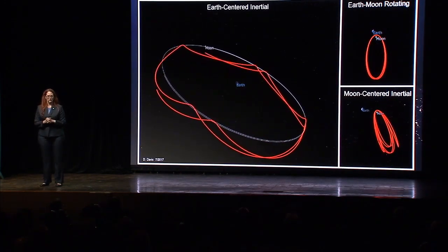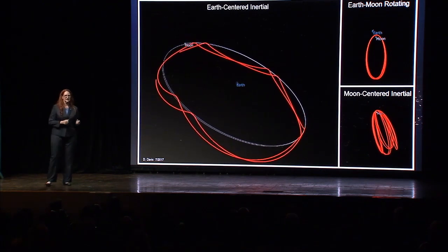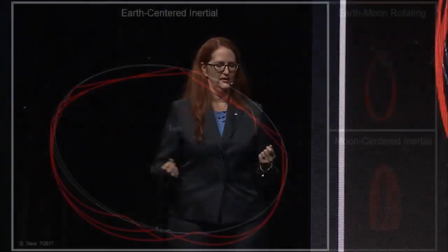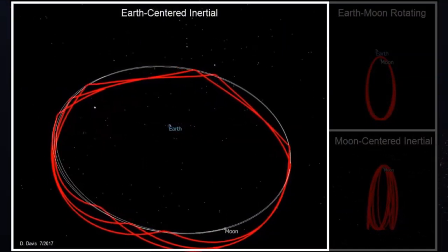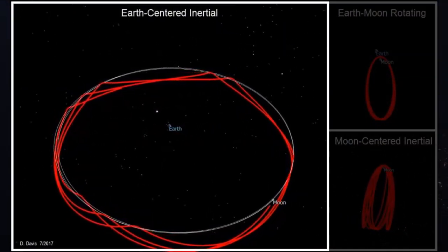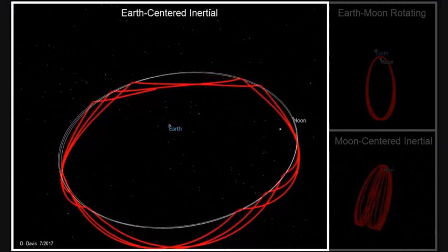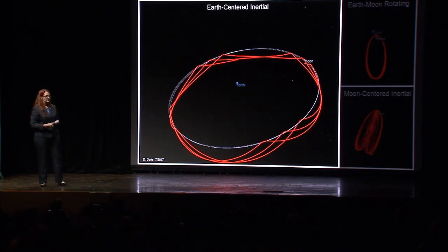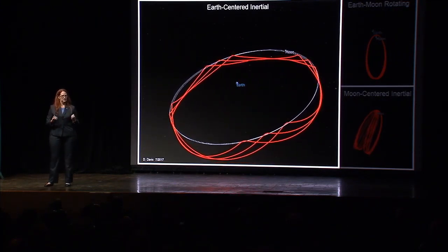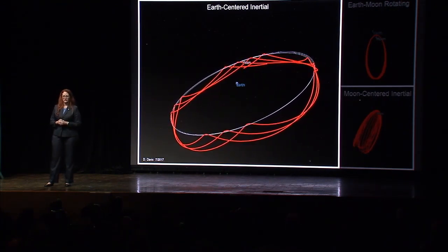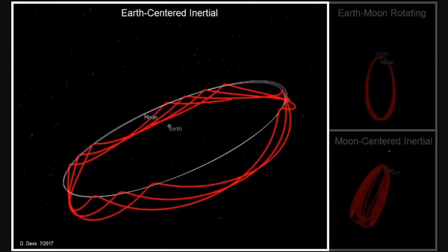The near rectilinear halo orbit is different than those circular orbits that I mentioned that Kepler discovered, like the orbit that the Moon takes around the Earth. These 3 views here show you that the near rectilinear halo orbit is an orbit about the Earth, but at the distance of the Moon, so it's tugged by the Moon. And these Earth-Moon interactions mean that for every 2 orbits that the Moon makes about the Earth, the spacecraft, the Gateway, in this near rectilinear halo orbit will make 9 of these leapfrogs over and under the Moon. And the period of this near rectilinear halo orbit, or the period between these leaps, is roughly 6.5 days, with only 4 hours out of that almost week spent out of view of the Moon's south pole.